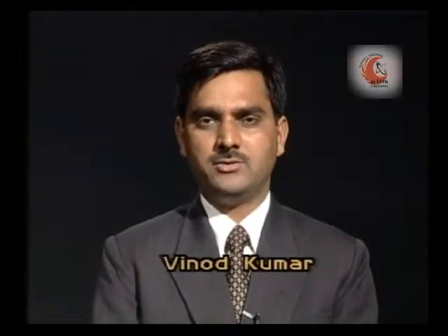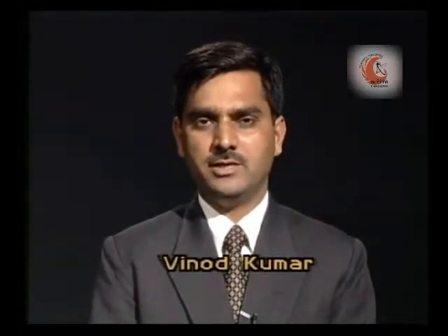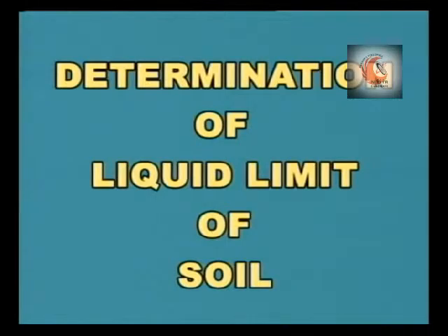Hello viewers, the liquid and plastic limits of soil depend on the amount and type of clay in a soil and form the basis for the soil classification system. The liquid limit of a soil is the minimum water content at which the soil is still in a liquid state, but has a small shearing strength against flowing, which can be measured by a standard procedure. In this program, we shall demonstrate the determination of the liquid limit of a given soil.